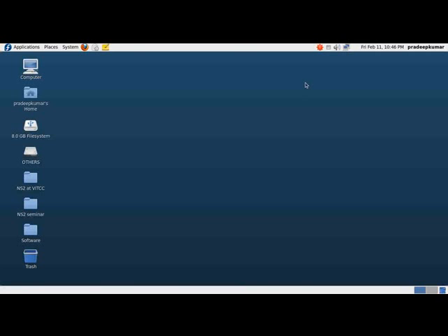Though there is a software called Xgraph which comes along with the network simulator too, it needs some kind of manual processing. But with Tracegraph, there is no manual processing at all. You give the input as a trace file, and the software will take care of the entire scenario. Now we will see how to install Tracegraph in Linux.